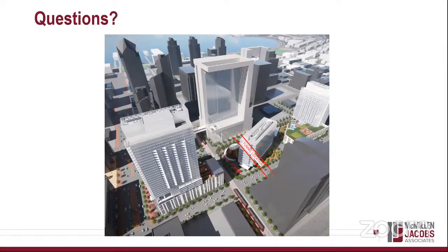Okay, we have a question about safety concerns. Are there major safety concerns with SEM versus other methods, pros and cons? For sure. There's definitely safety concerns with SEM methods because generally you're working at an open face, whereas with some mechanized tunneling methods, that face is protected with a cutter head or some other method that personnel don't need to go up and access frequently to work at the face, to install support.